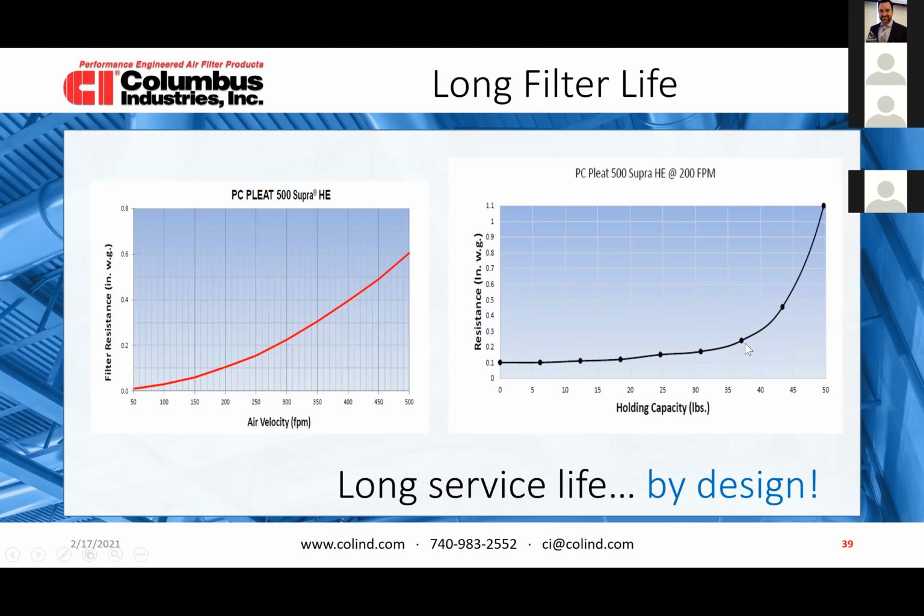So you would understand, if you look at the filter, that we do all we can. There's an area that we hide from the airstream, and we accumulate as much as we can. We make the filter have turbulence within the layers, but also within the construction of the pleats themselves. So there's turbulence within turbulence. And that way we get that longer life without gaining too much pressure drop.